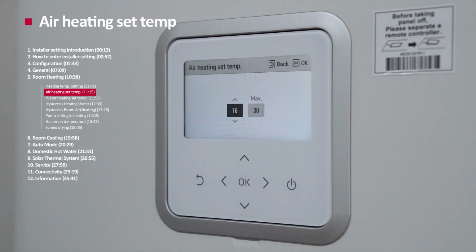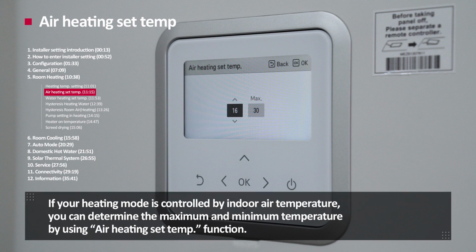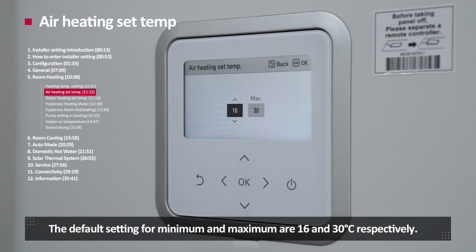Air heating set temperature. For the heating mode, the heating temperature can be controlled based on the indoor air or water temperature. If your heating mode is controlled by indoor air temperature, you can determine the maximum and minimum temperature by using air heating set temperature function. You can set the minimum temperature between 16 and 22 degrees Celsius, and the maximum temperature between 24 to 30 degrees Celsius. The default setting for minimum and maximum are 16 and 30 degrees Celsius respectively.